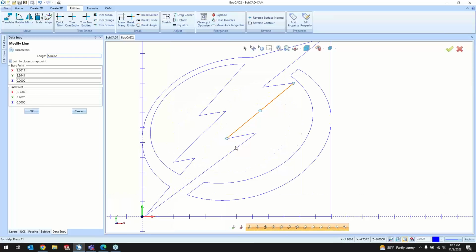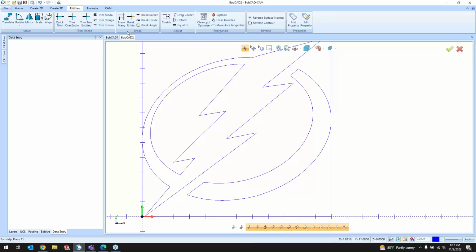Now in version 35, we can also drag and translate the line or arc by clicking on these certain snap points. If I click on the midpoint here, I can drag it from the midpoint and move it wherever I want. Then cancel to undo it.